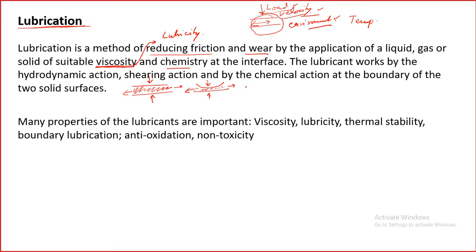So the viscosity will play a very important role, because under a dynamic situation, the viscosity will ensure that a thickness of the fluid film always remains at this contact point. And the main thing is that in lubrication, if the two solids come in direct contact, then the lubricant is not working. So there is a very strong action of viscosity, and we have to ensure by selecting a lubricant of sufficient viscosity so that a fluid film can always be formed.